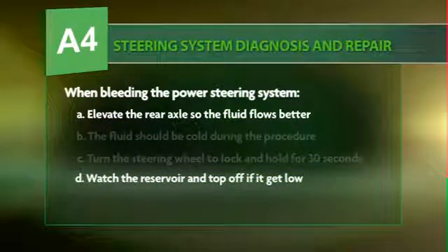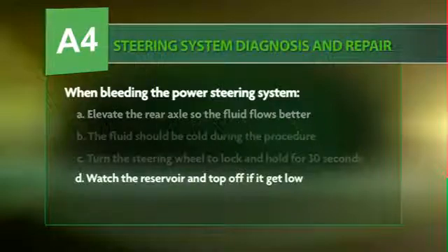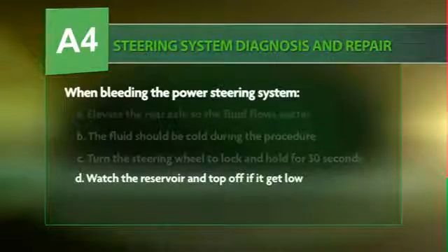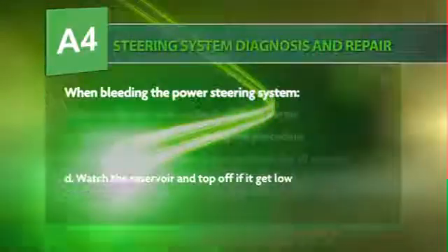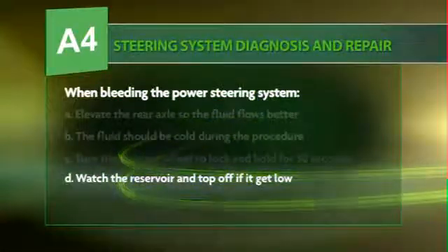Raising the rear axle so the fluid flows better is actually the opposite. If you want to get the system filled better, you want to raise the front end up. So A is eliminated, and the correct answer, of course, is that you want to watch the reservoir as you run the engine and turn the wheels back and forth, but no, don't hold it for 30 seconds at lock to lock. Watch the reservoir and top it off as it gets low as you bleed that system and flush it out with fresh fluid. So the correct answer to this question is D. Watch the reservoir, top it off as it gets low.